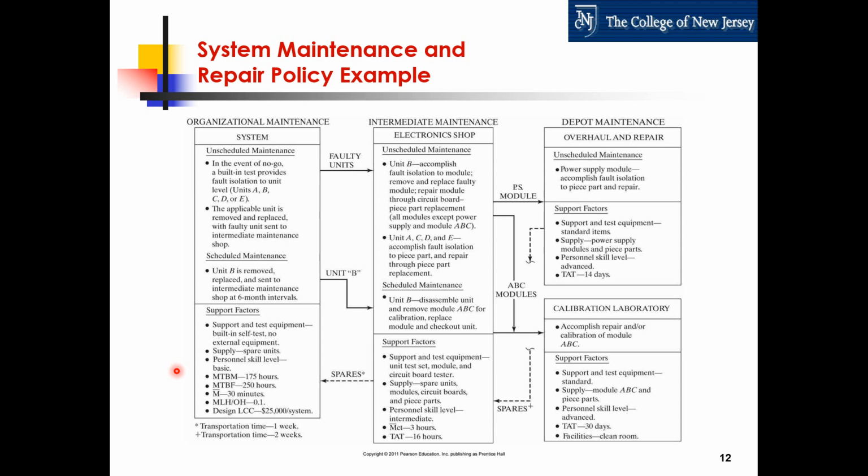If we find that we are maintaining this more often, that starts eating into our support budget, and we have to ask why is that? That is an issue. We also want mean time between failures to be 250 hours. Those are specific targets that can drive design decisions in the design of the system.